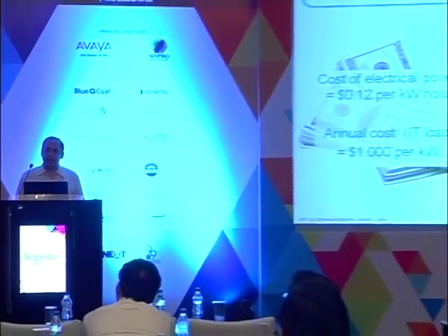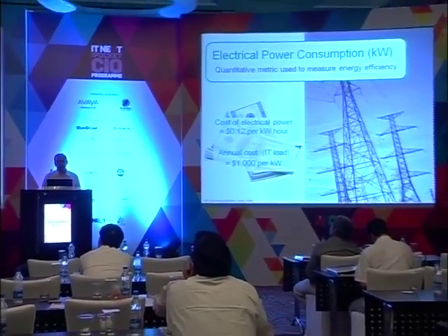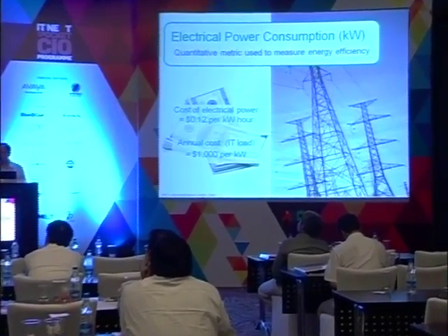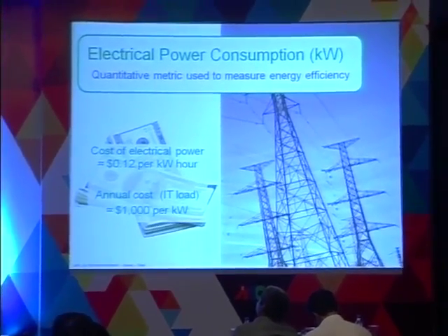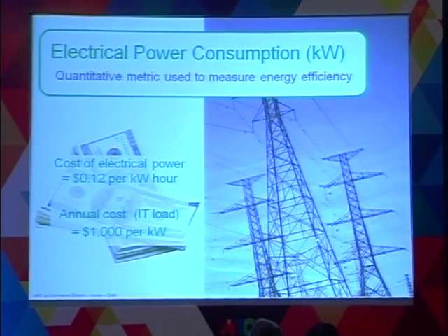How big is this hit? If I just start focusing on the efficiency of a data center and take the metric of only energy, how expensive can it get? What you see is approximately the average cost of electricity in the US, 12 cents, which translates to approximately $1,000 in energy cost for a year for every kilowatt of IT that you power. Per kilowatt, $1,000 does sound steep, right?